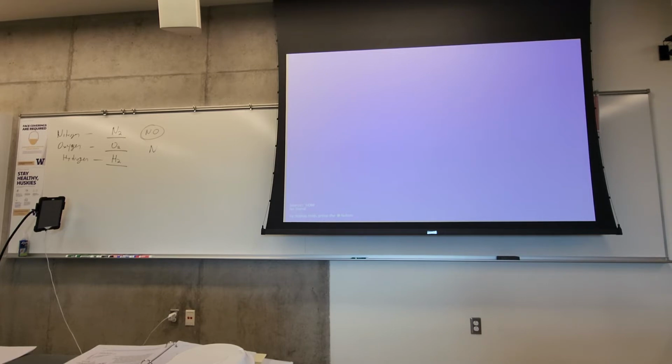And then the dry bulb temperature was 93 degrees Fahrenheit. Enthalpy was 45.1 BTU per pound mass of dry air. For number two, right? So we have dry bulb temperature. Enthalpy was 45.1.